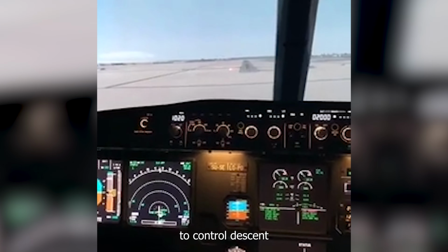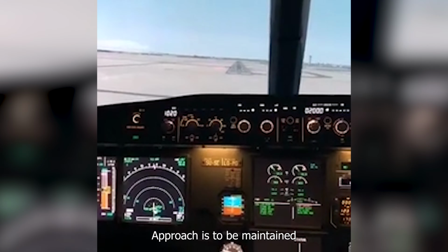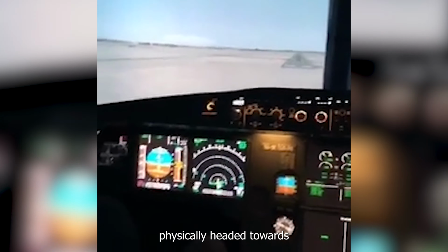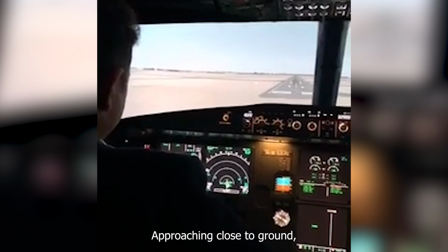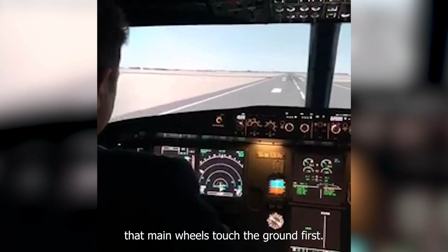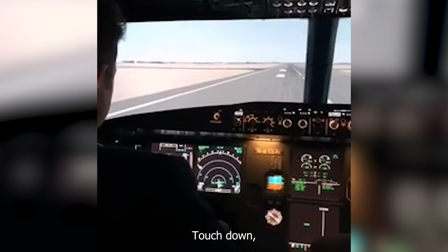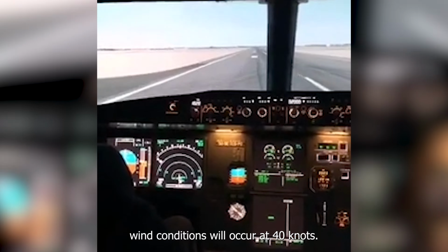Use throttle to control descent and attitude to control speed. Approach is to be maintained in a manner that the aircraft is physically headed towards the threshold or touchdown point. Approaching close to ground, slowly raise attitude aiming to land the aircraft in a manner that main wheels touch the ground first. Touchdown, under normal wind conditions, will occur at 40 knots.